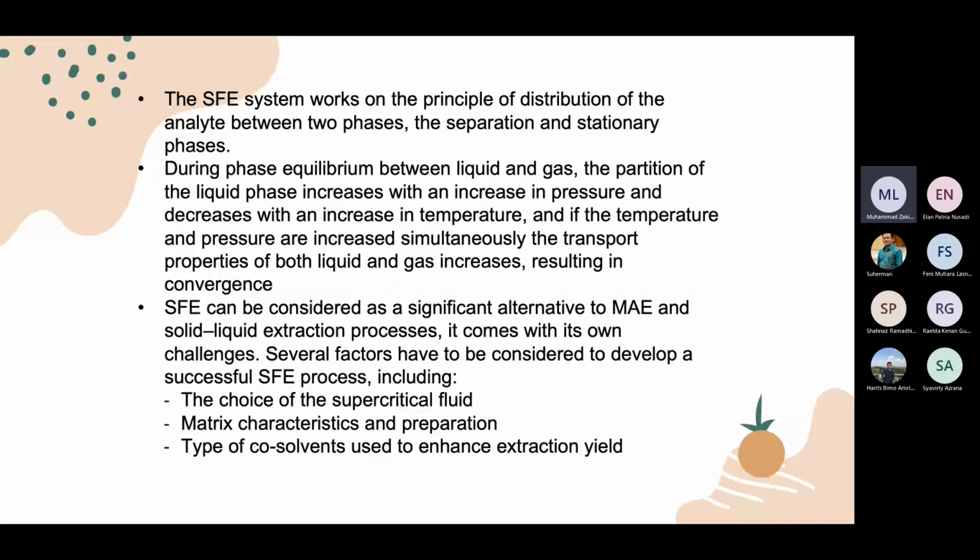It comes with its own challenge. Several factors have to be considered to develop a successful SFE process, including the first one is the choice of the supercritical fluid. Another one is the sample characteristics and preparation. Another one is the type of co-solvents used to enhance extraction yield.